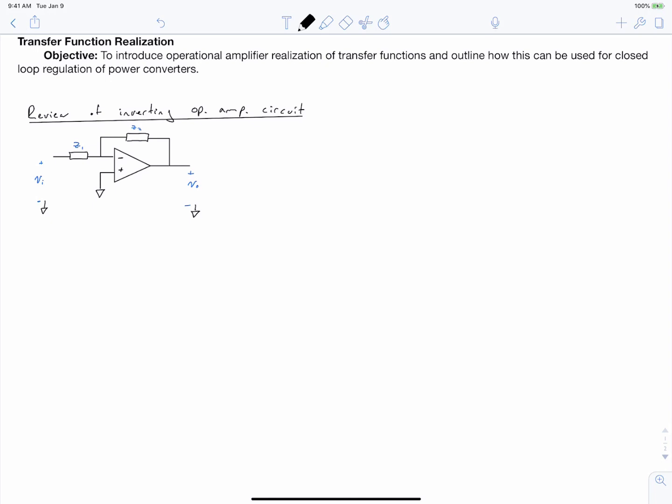in a voltage signal. And why are we interested in voltage? Well, that is the language of electrical engineering. That is how we can implement our feedback regulator for our power converter, is by measuring a signal, so maybe we're measuring current, converting that to a voltage, and then designing an analog circuit that can manipulate that to be the transfer function, to give us a regulator response to an error signal, that is the difference between an input reference and the measured quantity.